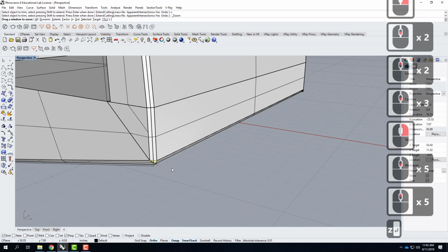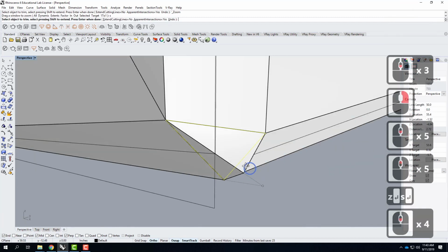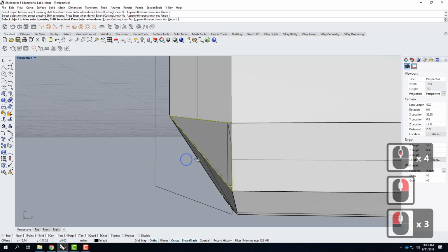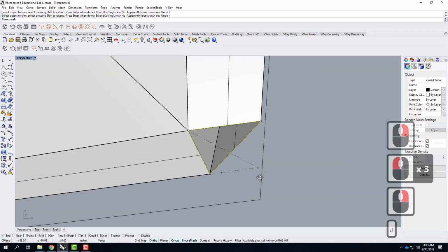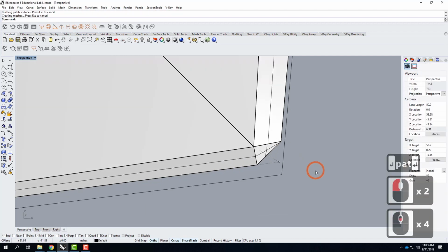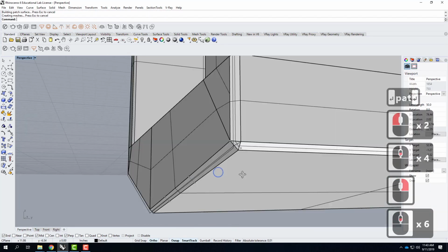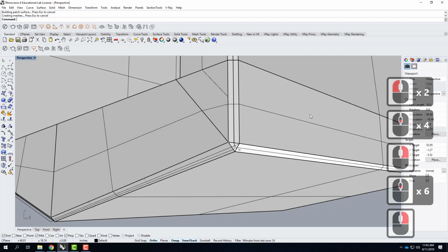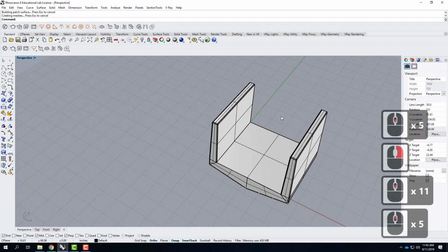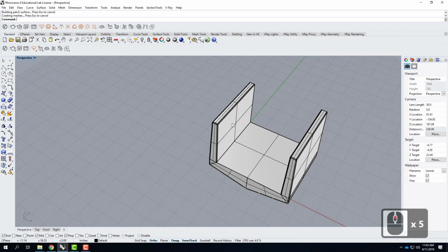Remember the zoom followed by S for selected to recenter your view to help you see, oh, there's the pieces that I need to get rid of, there and there. And now those are clean, and we could patch that resulting piece with another little surface. So if you were going to chamfer the bottom, but again, that's not required. Okay? So the purpose today is to go through and to practice with all of these points. That's really my goal.